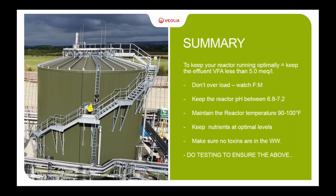So just to look at a general summary of some things, the key thing to look at, especially when you're running an anaerobic system, is your effluent VFA. If you're only going to do one test, we'd say do the effluent VFA test. As we went through, there are a lot of different tests that you can run on a daily or weekly basis.